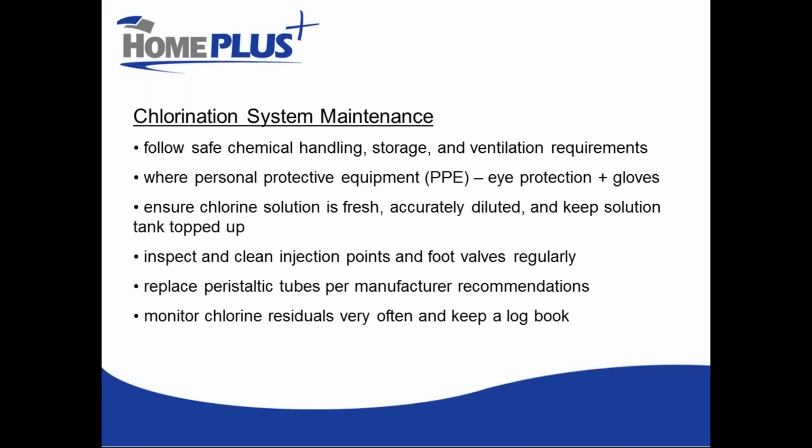Follow safety precautions. We're using harmful chemicals here. Wear the appropriate protection, ventilate properly, etc. Again, always ensure your chlorine solution is fresh. Clean and inspect your injection points, foot valves, and check valves that are contained within those regularly.